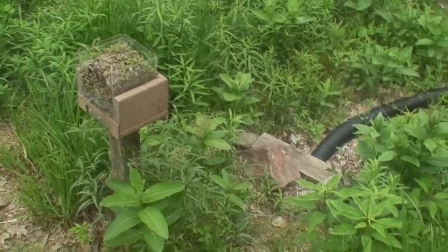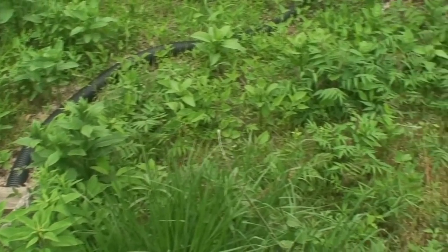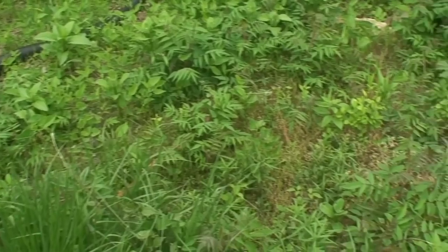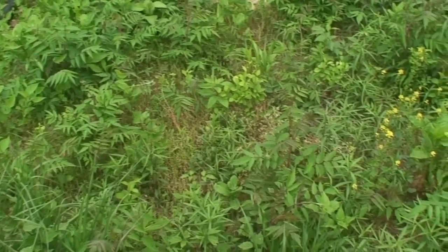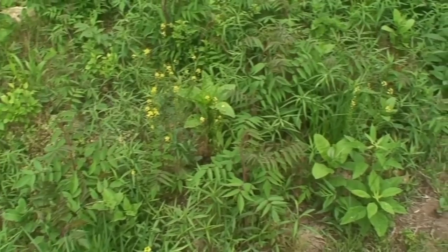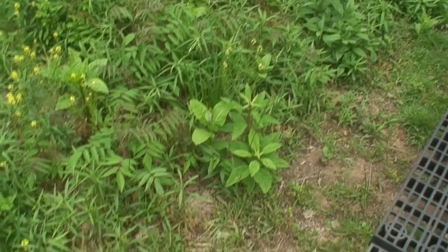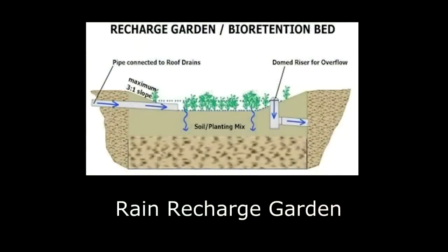We have a rain garden, which is right here, which collects the water from the roof or from the pavement that we're standing on and allows the water to flow into there so it can be absorbed by the plants that we see behind us, or it can infiltrate back into the ground or evaporate through the atmosphere. Rain gardens are designed to get rid of the water that is stored in them in 72 hours. That prevents any concerns with mosquitoes.